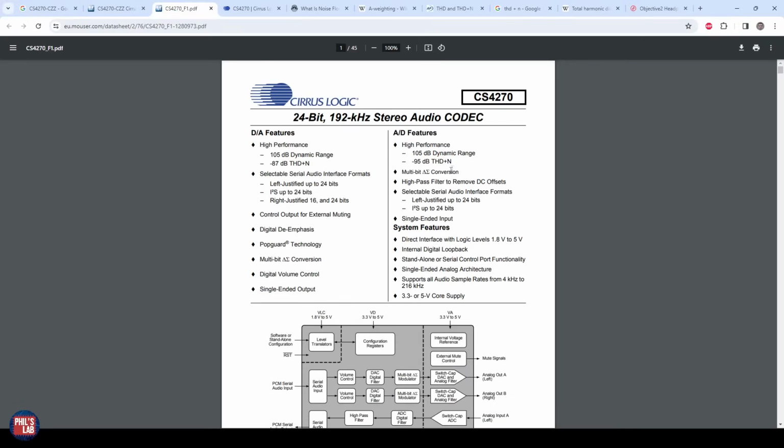We can also look at the codec datasheet, and that lists a baseline of the minimum THD+N levels at minus 95 dB. So that's what we're at least minimally bounded by, of course, not taking into account all of the other circuitry that's in our design.